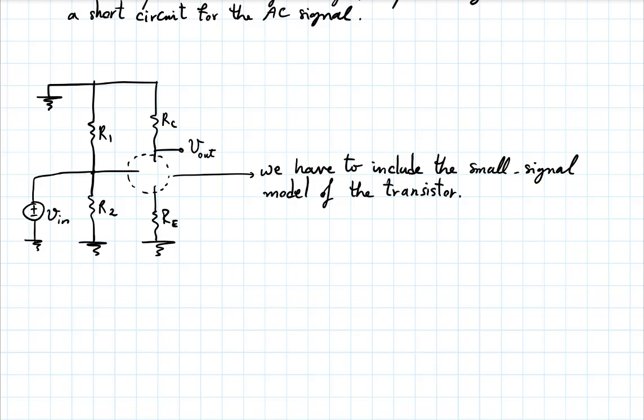Well, it's a conductance, so it's some current divided by some voltage. But it's not the conductance of one element. It's transconductance. It's the output current divided by the input voltage of the transistor. But it was a small signal transconductance. It was, in fact, the small signal output current divided by the small signal input voltage.